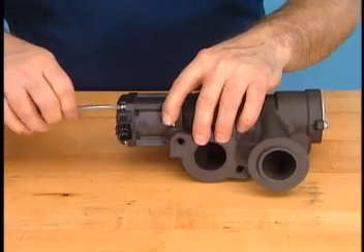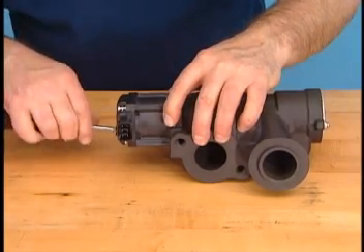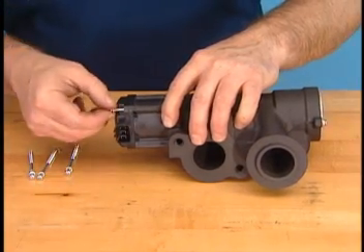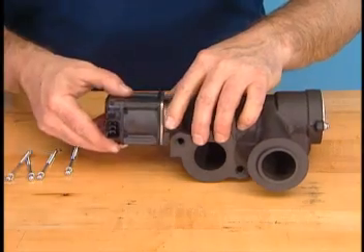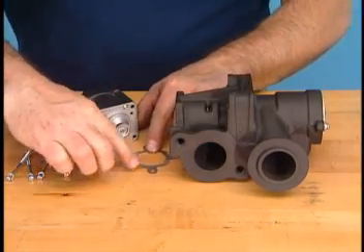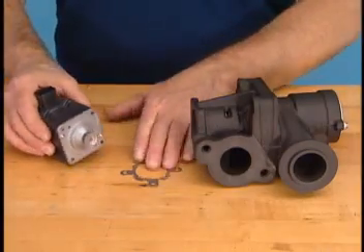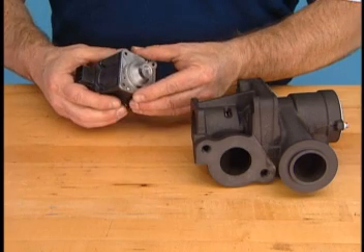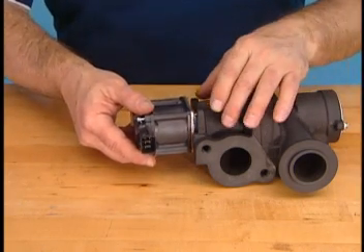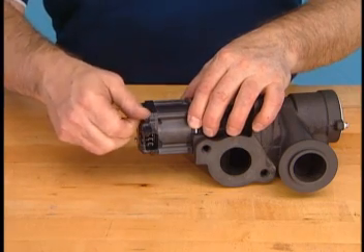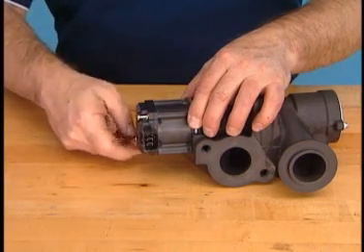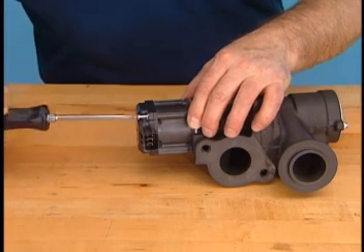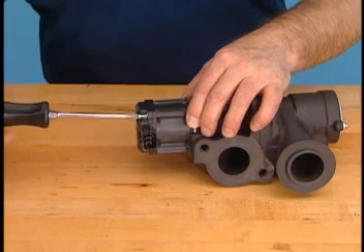To service it, remove the EGR valve assembly. Then remove the cap screws connecting the EGR valve actuator to the assembly. Remove the EGR valve actuator shim if required. Replace the EGR valve actuator shim before installing the new EGR valve actuator. Place the EGR valve actuator on the EGR valve housing. Insert the 4 cap screws and hand tighten them. Torque to specification. Refer to the service procedure for the correct torque specifications.